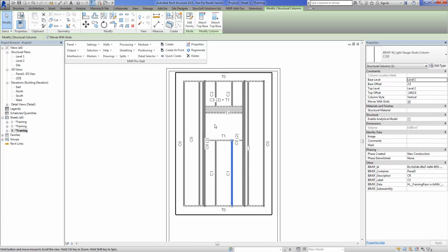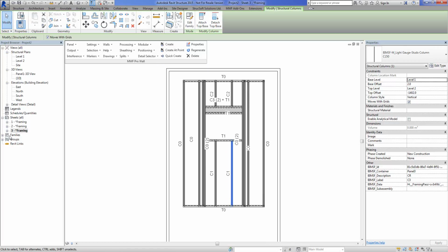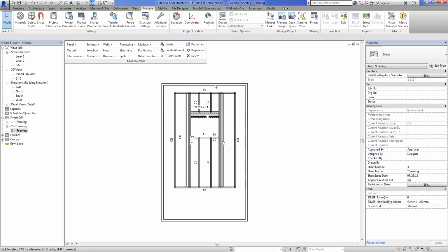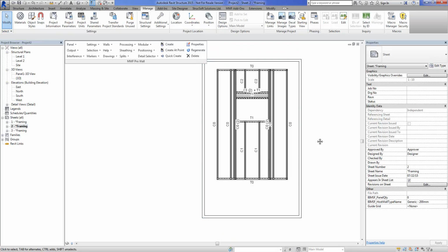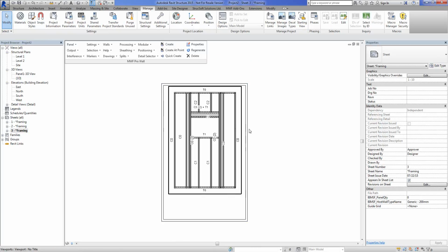But it gives you a good idea of the proximity grouping and how effective it can be. If we compare this one to this one, see a lot of clutter up there, and even this one still not quite where we'd like it to be. But as we end up evolving and adding those shifts, it looks quite good. And again, we wouldn't be able to achieve something like this with Revit tags, because they'd be just placed smack in the middle of each of those members, and that would cause quite a bit of clutter. So proximity grouping allows us to group members together and to save on the clutter. And actually, the results look quite nice.